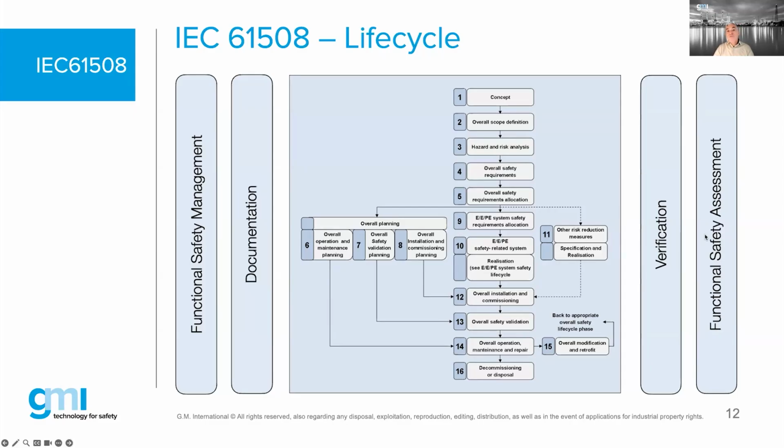If it is a SIL 2 requirement on that interface, then it will be an independent department. And only for SIL 3 is there a requirement in the standard 61508 for an independent accreditation by an independent organization. The independent organization is only a requirement for SIL 3. That investigation or assessment will lead to a result, a report, and the report result may then be reflected in a piece of paper called a certificate.